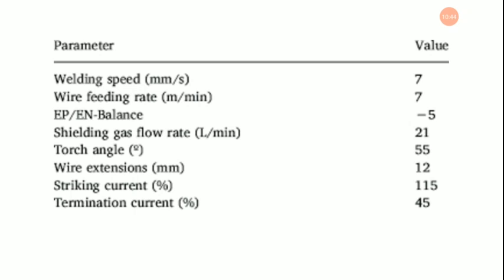Now, the process parameter welding speed is not as significant as the others. As the welding speed decreases, the penetration value goes on increasing. This is mainly because at lesser speed, complete melting of submerged filler metal and base metal leads to complete diffusion of filler metal into base metal and forms a perfect joint. As the frequency increases, penetration goes on increasing for better diffusion of filler metal into the base metal, so the penetration value increases, but with further increase in F from 6 Hz, more penetration than required leads to undercut and decrease in penetration value.